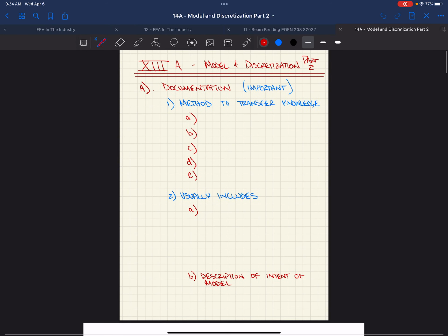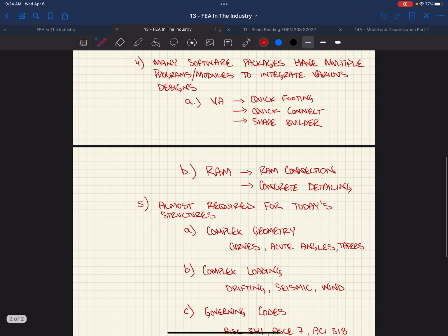It's all architectural. That was all a rigid diaphragm, wasn't it? Yeah, everything's concrete. But we never look at it, so that's something you can decide as a designer too, right? The code allows you to make assumptions, whether it's flexible or rigid. With the power of VA and finite element analysis, you can really try to match the mathematical model to the real world, right?